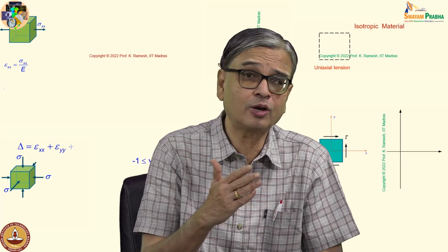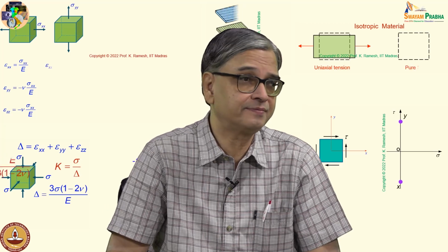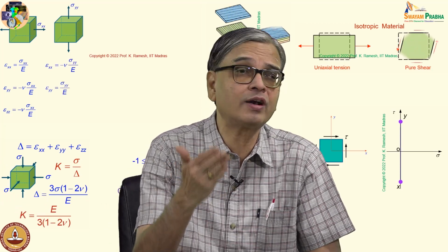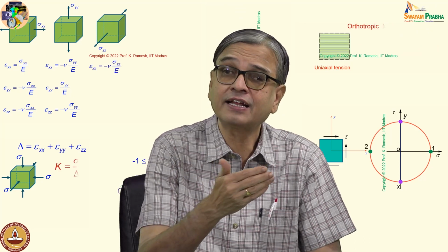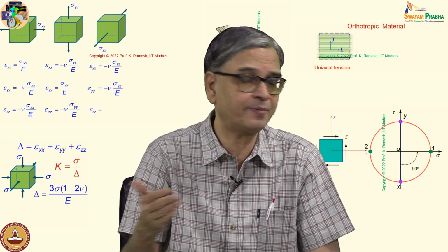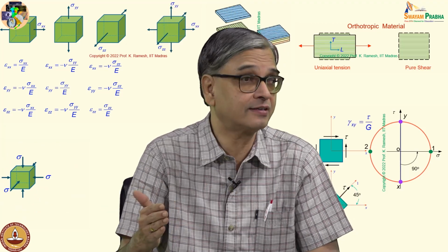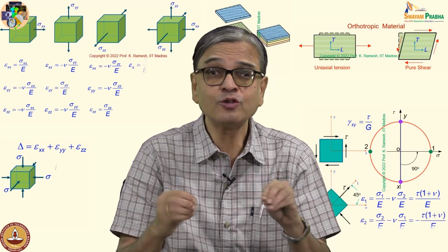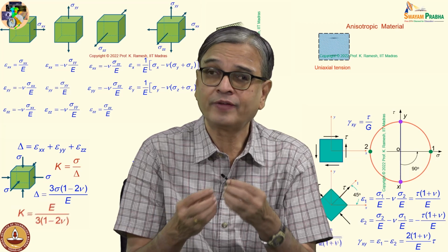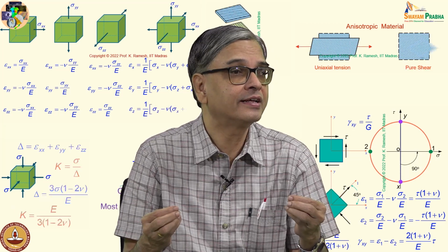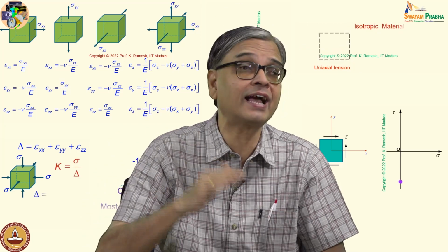And we have also looked at one more way to make the specimen fail. If I apply the load repeatedly, then also after some number of cycles, depending on the material and depending on the load, you find failure has occurred. And with your hand you cannot apply a very high load, you can easily understand. So when I do repeated loading, I am forced to operate at lower loads in actual service.